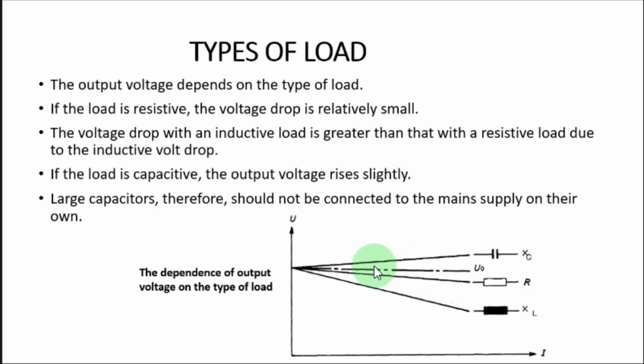So with that we end this lecture on the full load, or rather short circuit and open circuit test, and how to find the parameters. So if I just summarize what we have discussed so far, by using these two tests we can find the equivalent circuit parameters of a transformer. So the two tests are called open circuit test and short circuit test, and if you know the equivalent parameters, then you can easily calculate voltages and current for different loads.